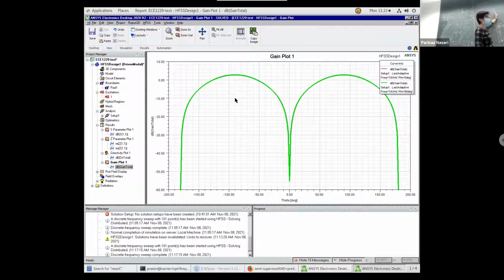Theta equal to 0 is where actually there is this null of the radiation pattern. So you have a null here, and then minus 80 and 80 are both this way. So you go from 0 to here. You have two because I assigned from minus 80 to 80 for theta. So we go from one null, get to this null, and then go back to the second. Yeah. Okay.